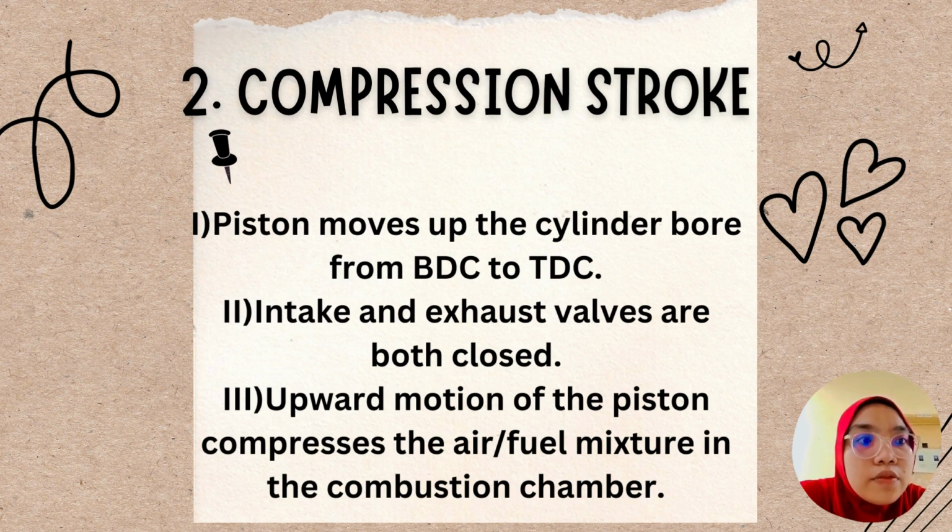Compression stroke. First, the piston moves up the cylinder bore from BDC to TDC. Second, the intake and exhaust valves are both closed. Third, the upward motion of the piston compresses the air or fuel mixture in the combustion chamber.